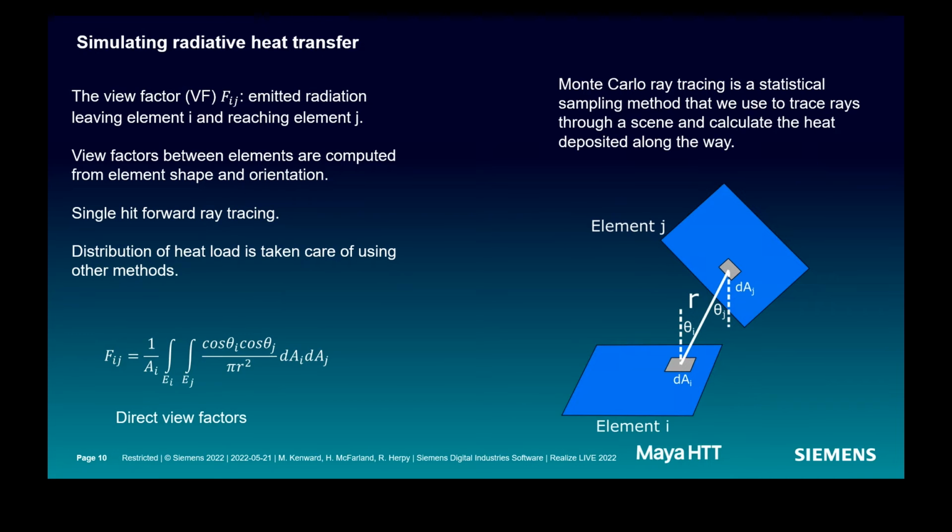So if you have a headlamp, for instance, the main light in the headlamp can see a fraction of the model, but then you have propagation of the heat or the electromagnetic radiation through the model, and thus distributes heat in the headlamp itself. So the view factor calculation is a simpler version of being able to calculate how heat is distributed in the system.